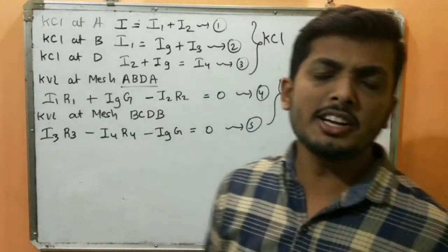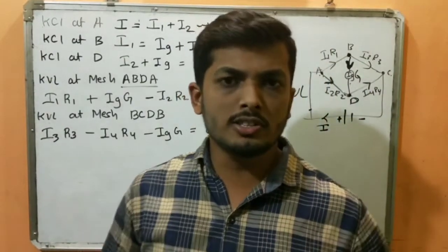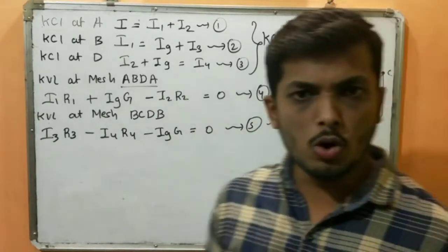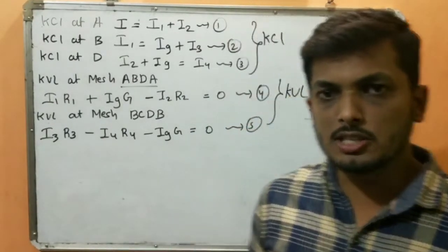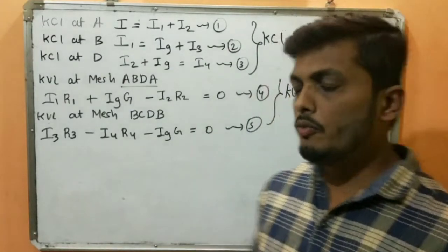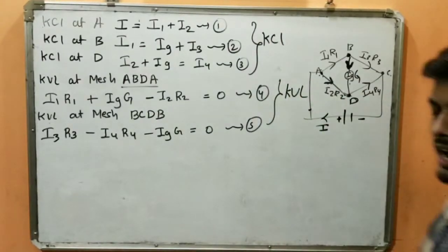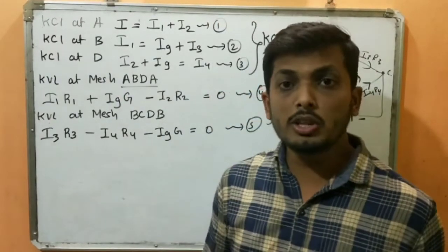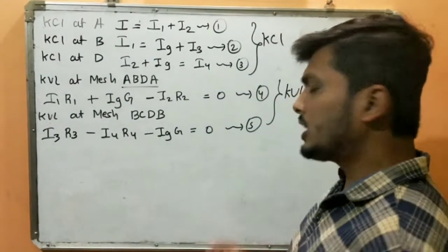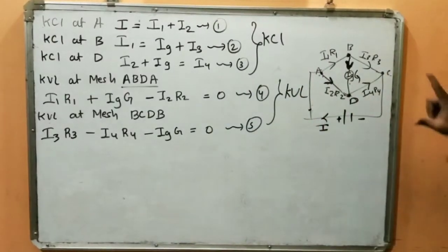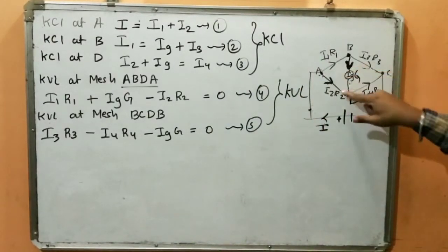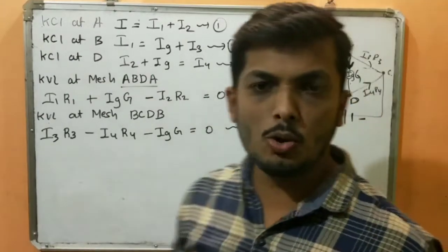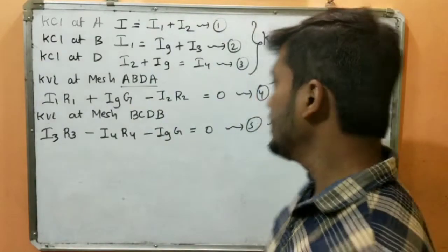So just understand Kirchhoff's current law and Kirchhoff's voltage law and simply apply them to this complex electrical network consisting of four resistors, out of which three are known and one is unknown. Now, as I told you, we are going to find the balancing condition, and you already know the formula out of it. But to satisfy the balancing condition, the galvanometer reading should be 0. Once the galvanometer reading is 0, only then will the balancing condition be satisfied.